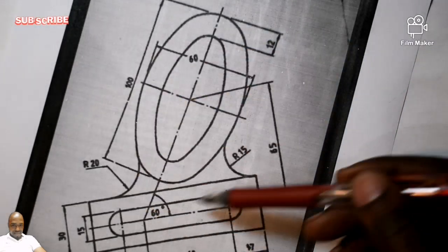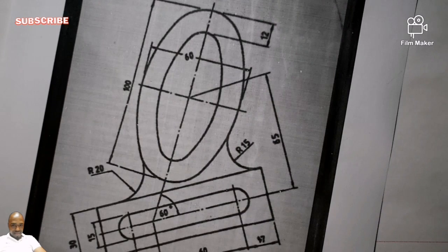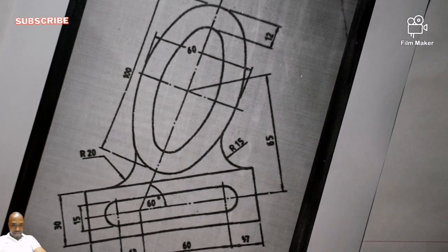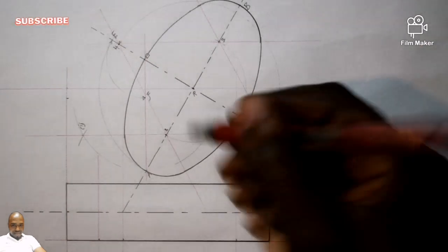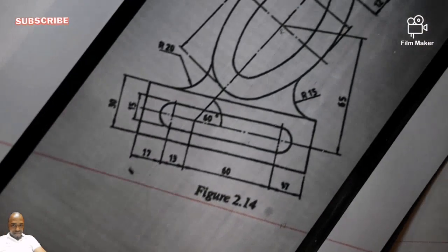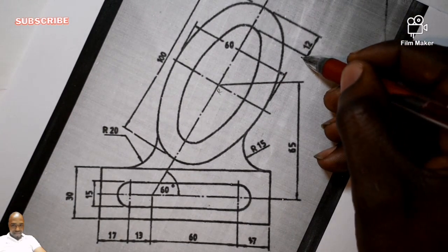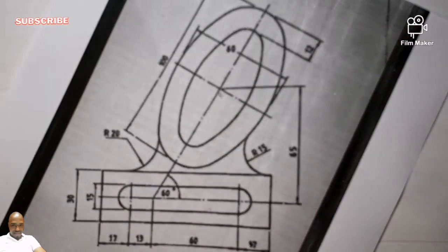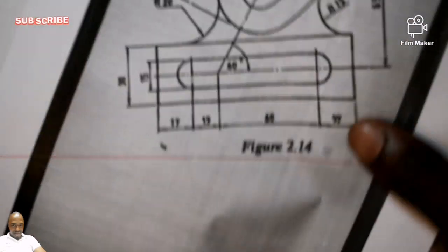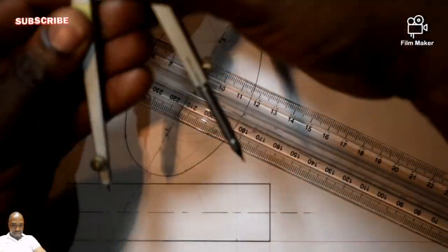The outer ellipse. But there is a small one inside there, using the very same reference point. You understand? So we are told, okay, from here till here is 12 millimeter. From here till here is 12. From here till here is 12. So it's the same. What am I going to do? Simply open my drawing compass to 12 millimeter.